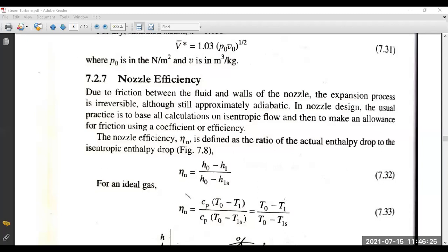Now, in an enthalpy-entropy chart, a Mollier diagram rather than the ordinary T-S diagram, what we find is that on the abscissa we plot the change in entropy, and on the ordinate the change in enthalpy. We find from the chart the two pressures: P0, the stagnation pressure, and P1, the outlet pressure.